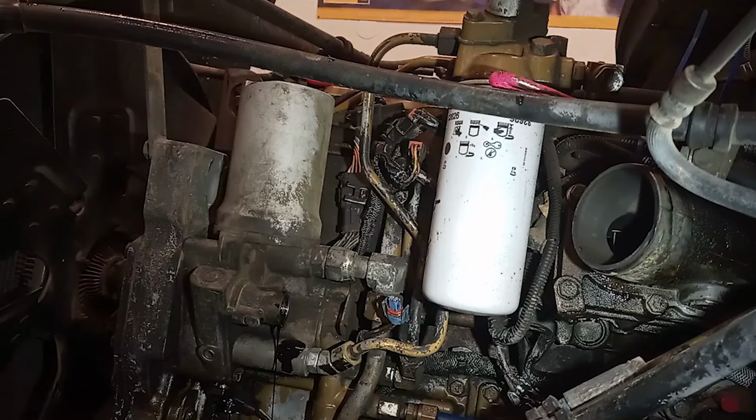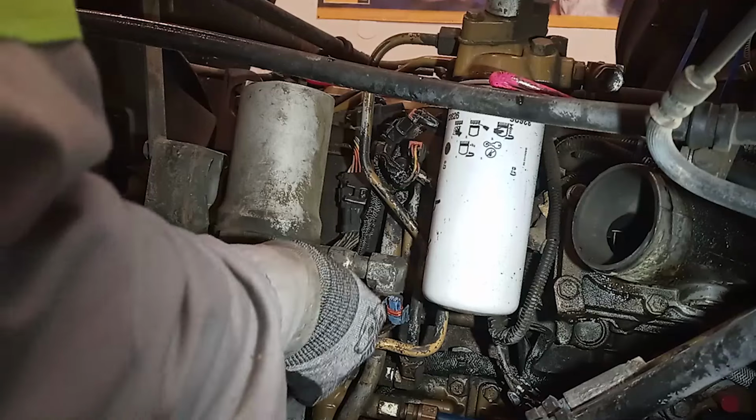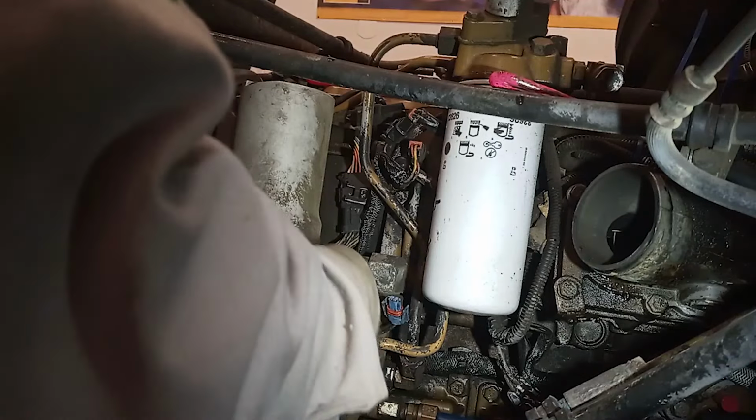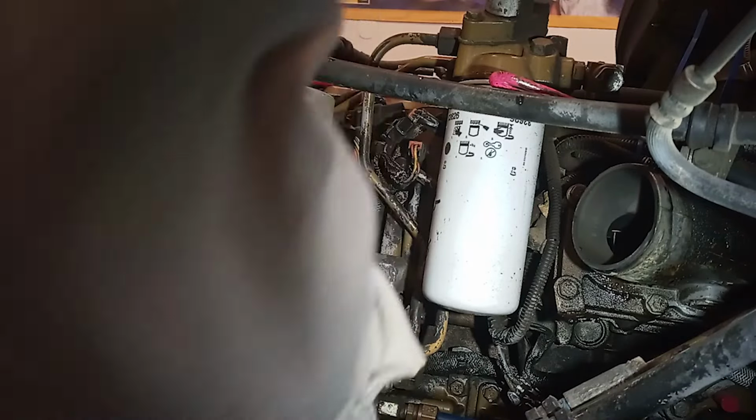Generally, I'd say we do a lot of the solenoids. Probably about 50% of the time it's the solenoid, about 50% of the time it's the pump itself. So hard to say. Like I said, if you have the newer style with the square head, you can't change the solenoid. You have to change the whole pump, no matter what.